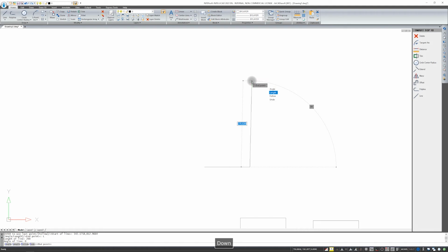But now please pay attention. First specify whether you're entering the length or the angle. I'll enter the length, that is the letter L, type in 500 and confirm with enter. Now for the angle. I will type 90. For a change, we will now choose the angle. I will enter 180 and the length will be 200. And now if I were to enter the angle, it would also be 90 degrees from the last entered value. But I'll just close it and another rectangle is drawn.